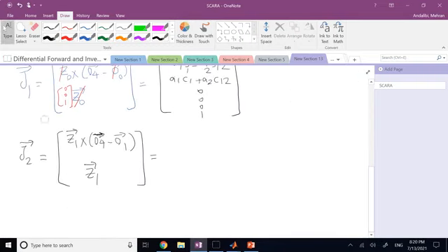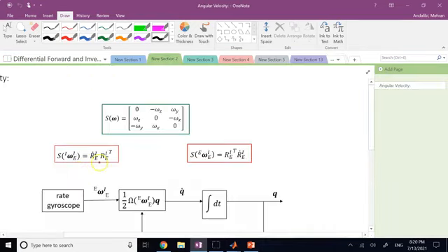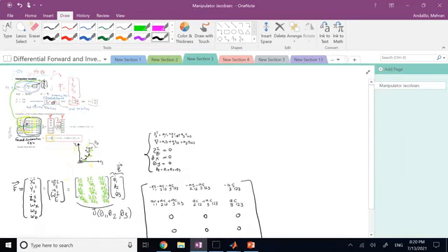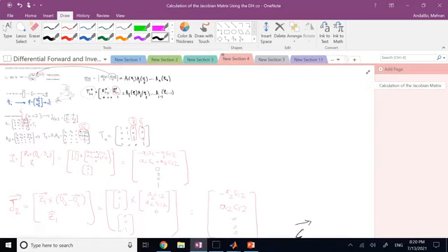For a computer, if you program it well, since they are very good, like MATLAB especially, at multiplying matrices and reading a column of a matrix, writing this and allowing it to calculate the complicated Jacobian matrix for robots with high degrees of freedom is going to be quite easier than actually calculating those functions for the angles that are not always trivial.